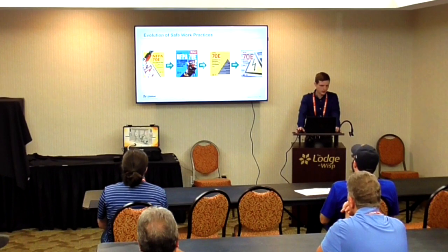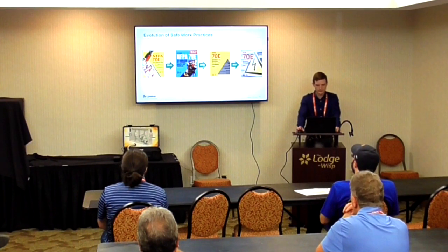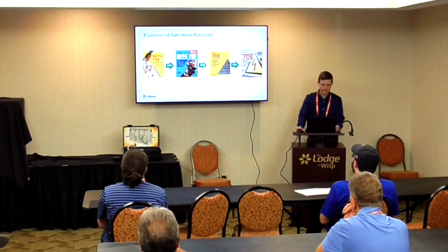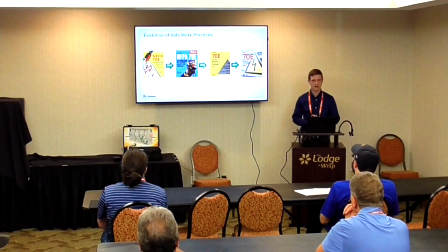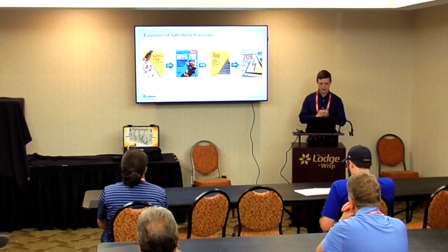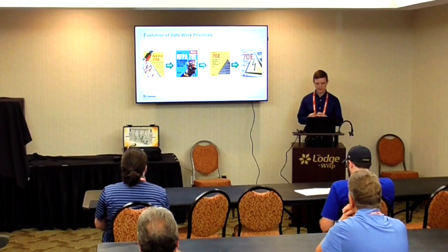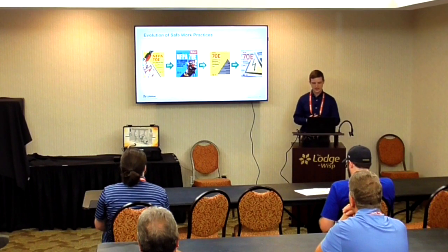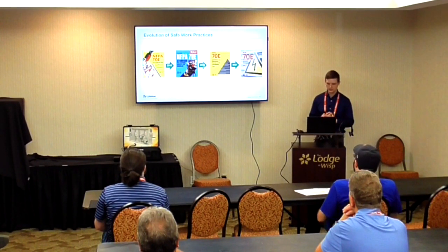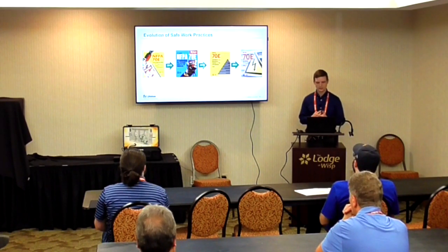Before we get to that though, I'm just going to cover some of the different iterations of the NFPA 70E. NFPA 70E has some comprehensive guides for establishing policies, practices, and procedural requirements. This is all for electrical shock and for arc flash incidents. They have an electrical safety program that is required to be developed and implemented, and then they have a requirement for a risk assessment. You'll see this commonly talked about with establishing an electrically safe working condition, things like lockout tagouts, energized work permits, and then the actual performance of the risk assessment.